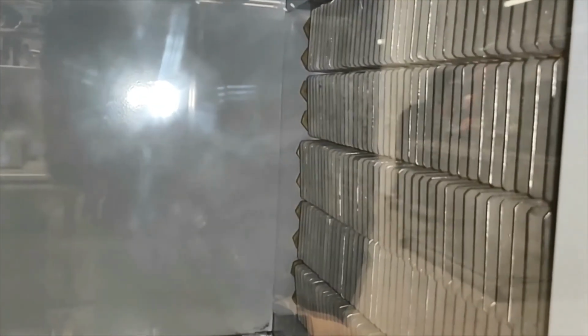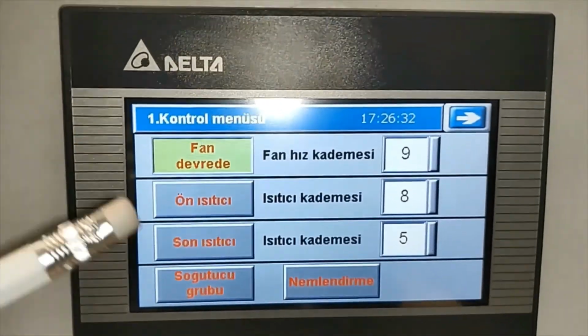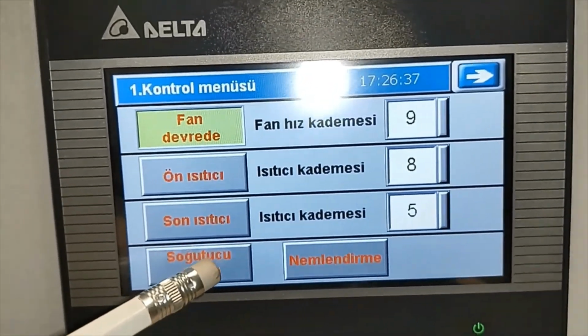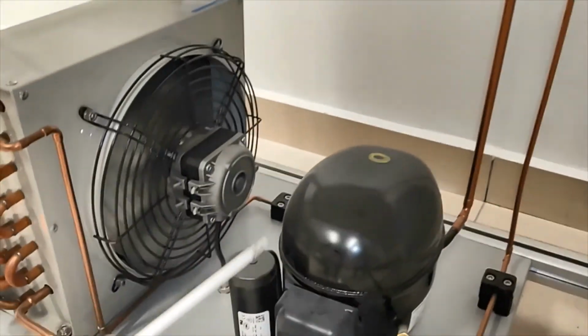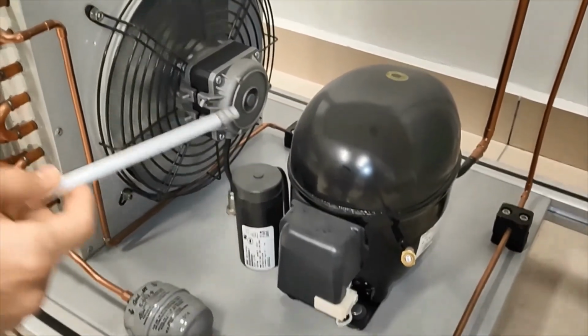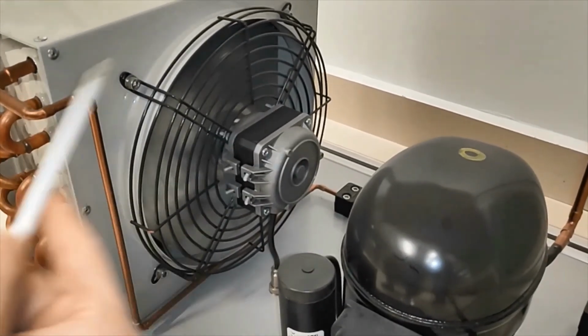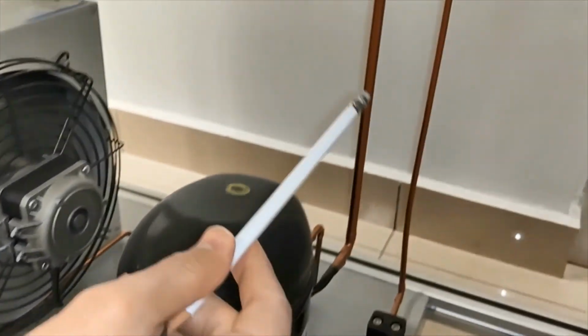Radial fan is switched on and it starts to operate. The sensor that is very next to the fan gives us temperature and relative humidity of the outside conditions. The air firstly reaches preheater, but preheater is not open, so temperature does not change. After cooler is opened, the temperature of air drops when reach the cooler. These are the refrigeration groups with compressor, condenser, filter and evaporator or cooler. This one, the cooler. These are the refrigeration group.